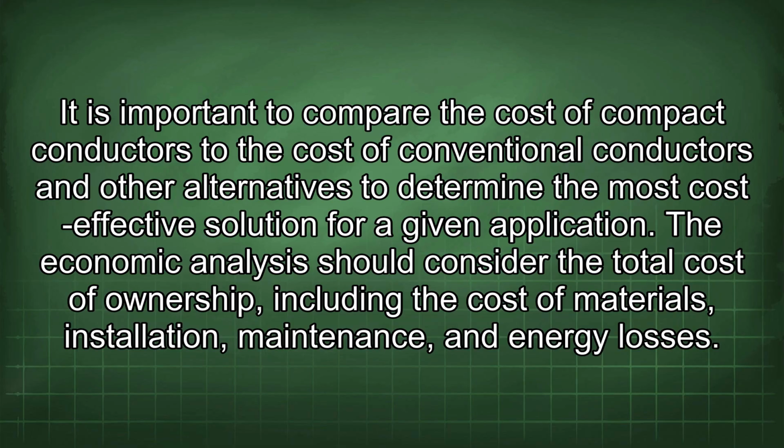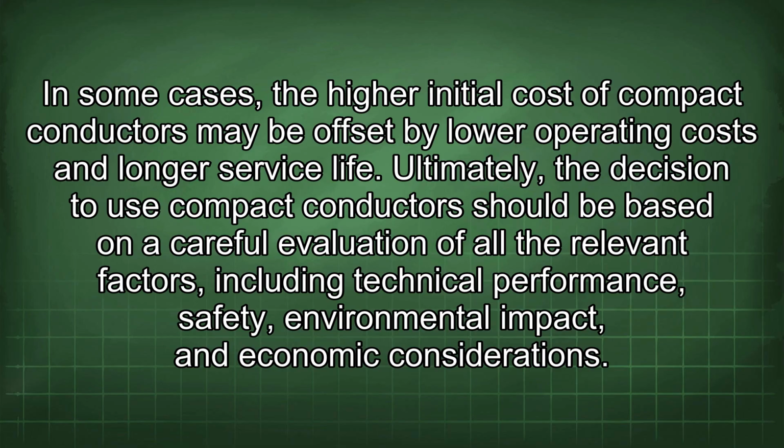The economic analysis should consider the total cost of ownership, including the cost of materials, installation, maintenance, and energy losses. In some cases, the higher initial cost of compact conductors may be offset by lower operating costs and longer service life.